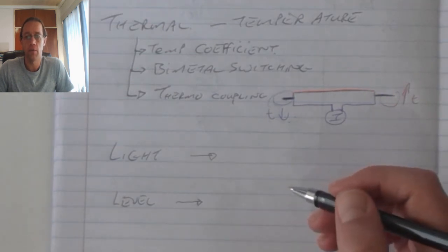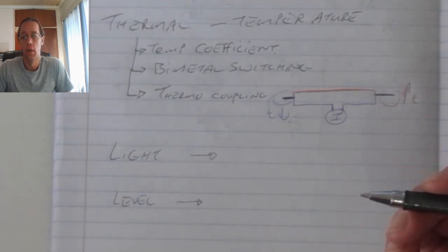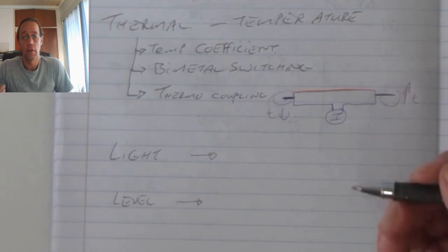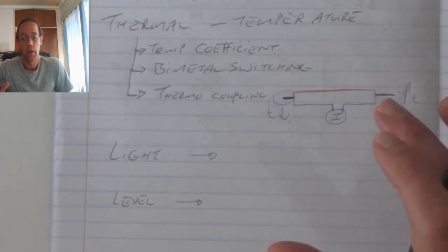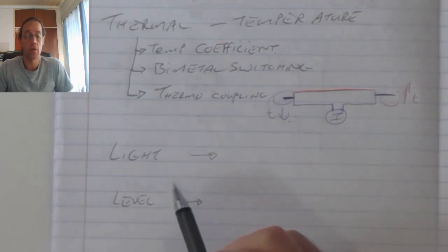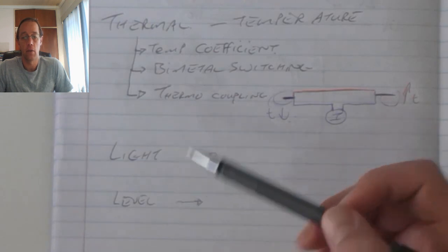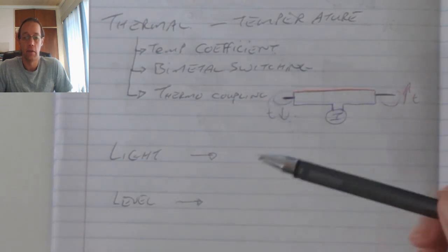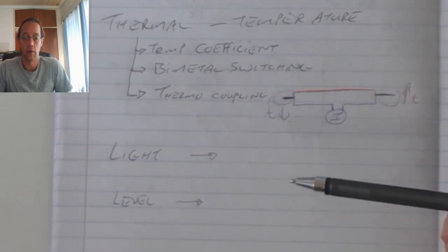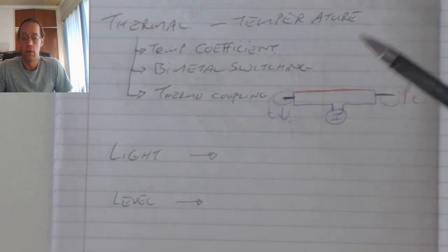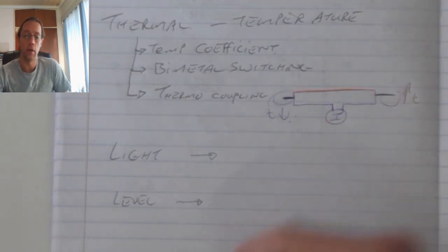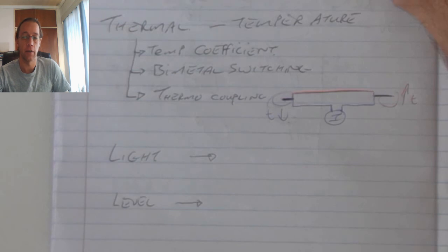The second type of level is, for example, a container that's filled with water, and then we can use the proximity sensor in order to measure the distance from the top of the container to the top of the liquid to determine the liquid levels inside that tank.